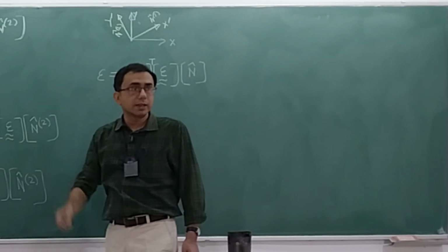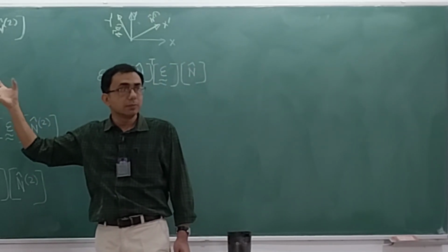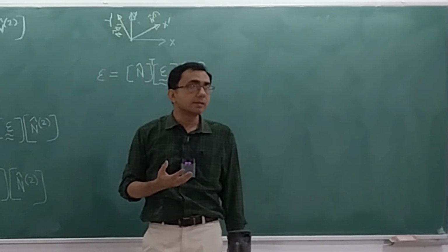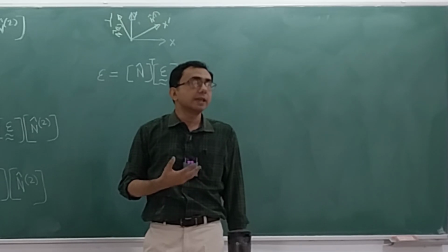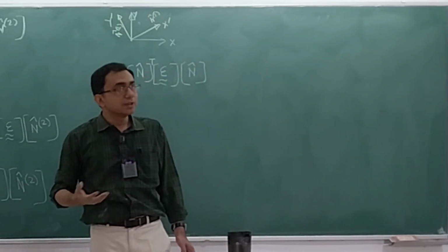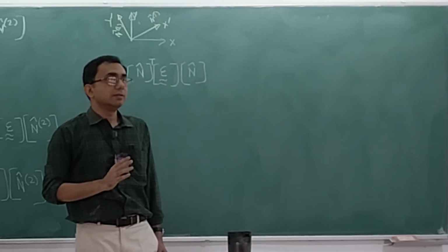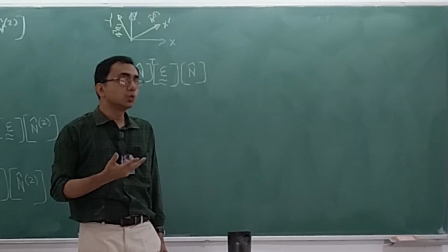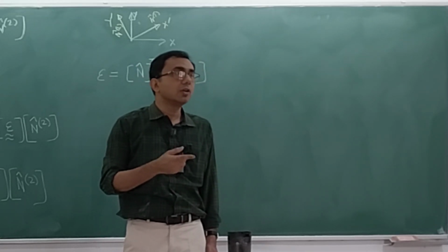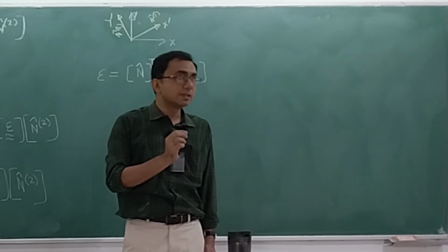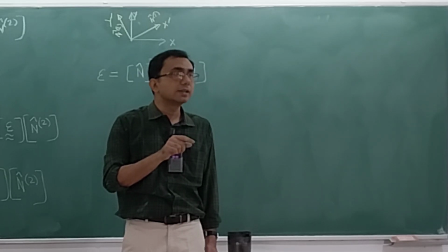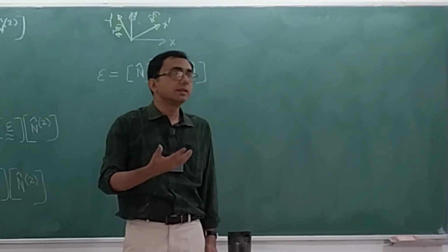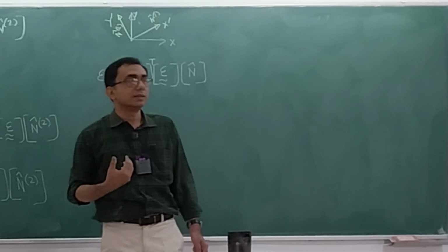For 90 degrees. The reason for choosing 90 degrees is that for shear strain, the fundamental definition tells us that the shear strain is the change in the angle between two elemental line segments which are initially at 90 degrees to each other. We don't keep on saying this because usually, and none of the textbooks tell us this, we just say gamma xy, gamma yz. But what is gamma xy? It is the shear strain corresponding to two elemental line segments which are oriented respectively along x and y. What is implicit and not explicitly stated is that the angle between those two line segments is always 90 degrees. Again, you have things like gamma yz, gamma zx, all of those have 90 degrees in between them. That is never stated explicitly, but now we are stating it.